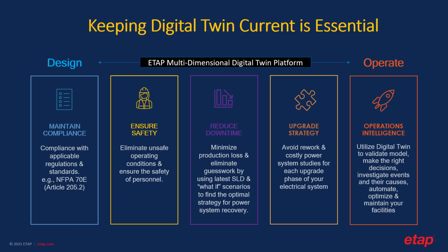An accurate single-line diagram will further ensure the safety of personnel work. Electrical safety consultants will typically ask for the latest single-line diagram for OSHA. Therefore, an updated single-line diagram is the most important fundamental material for any facility. Based on NFPA 70E on electrical safety standards at work, several studies, assessments, and evaluations require the need for us to update the single-line diagram so these activities can be carried out.